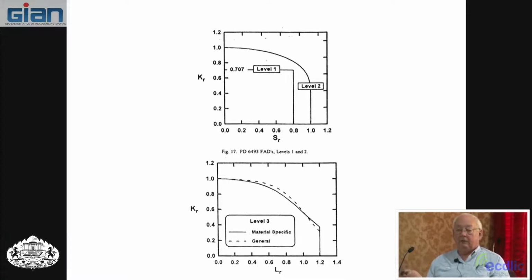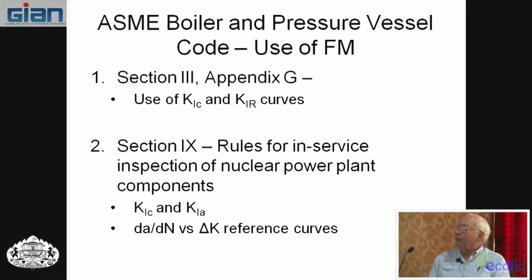You just go through step 1, step 2, step 3, and follow down the line, and then you don't need to know too much fracture mechanics. You have to know just enough to calculate stresses and that kind of thing. So those are 2 failure analysis diagram methods.